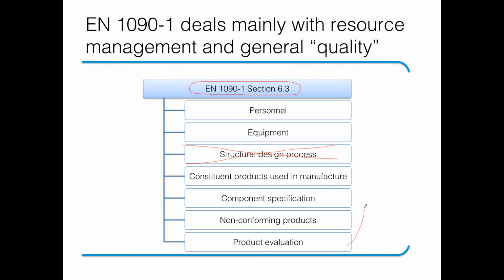And this relates to the fact that this structural steel product falls in the group 2+. If you remember what the requirements for the 2+ were, the manufacturer must establish an FPC system and then determine the essential characteristics in a thing called ITT, initial type testing, and then they must do spot checks during the manufacturing to make sure that the manufactured product meets the requirements of all the standards and is also according to those characteristics that you declare in the CE marking.